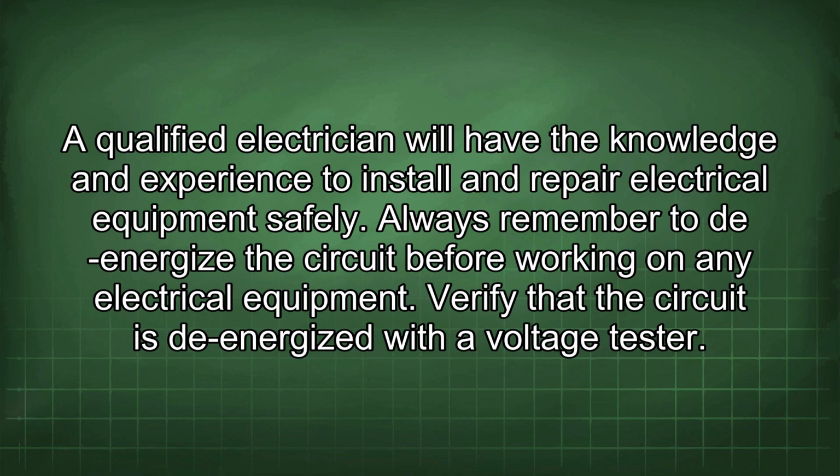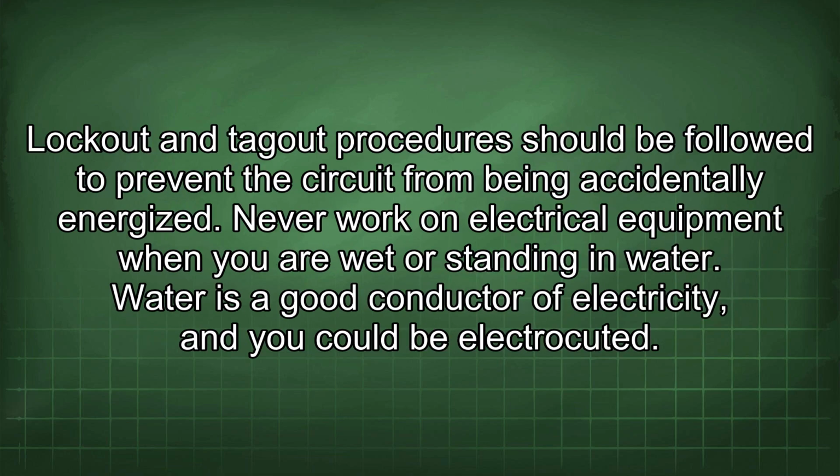Always remember to de-energize the circuit before working on any electrical equipment. Verify that the circuit is de-energized with a voltage tester. Lockout and tagout procedures should be followed to prevent the circuit from being accidentally energized.